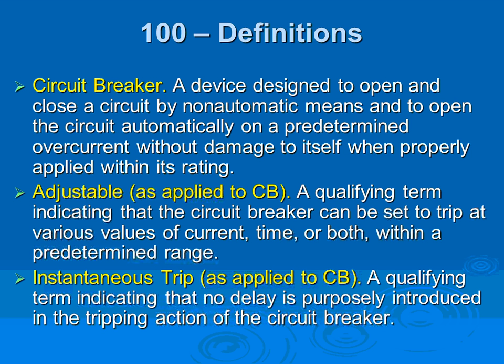You can use it as a switch, or if you have a short circuit, it trips. The only thing that confuses people with a circuit breaker is that it has a range. So why did it take my circuit breaker that long to trip when I have an overload? Because it's a range. It sits there, it has to heat. If it's thermomagnetic, that's the delay. There's delay in it.